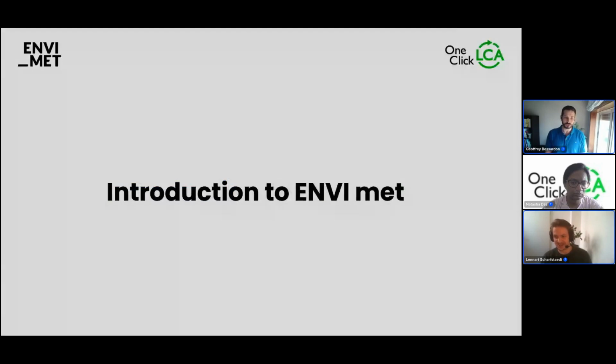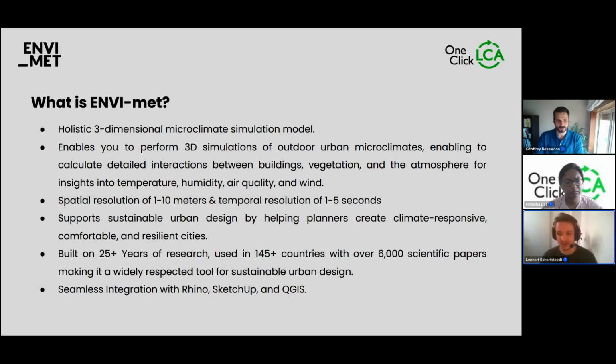So, all right, thanks, Geoffrey. As Geoffrey said, we're now going to dive a little bit deeper into ENVI-met and have a look at what it actually does, how it works. Just some bullet points for the start. ENVI-met is a holistic three-dimensional microclimate simulation model, which enables you to perform 3D simulations of outdoor urban microclimates, and we can enable with this tool very detailed calculations of the different interactions between buildings, vegetation, and the atmosphere.